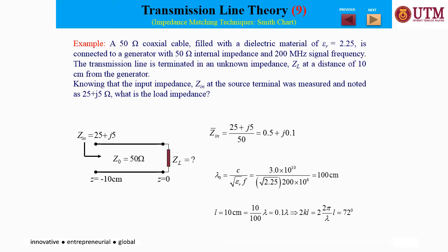And in this slide, to calculate lambda, it's c over f. You know that lambda equals c over f0, but if you have a dielectric material separating the transmission line or field within the transmission line, you need to consider the permittivity of the transmission line. So lambda now becomes lambda effective, c over, considering the dielectric material permittivity, and also f, the frequency of operation.